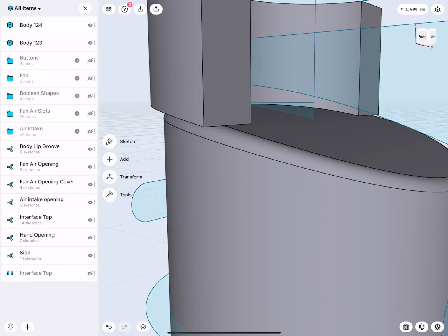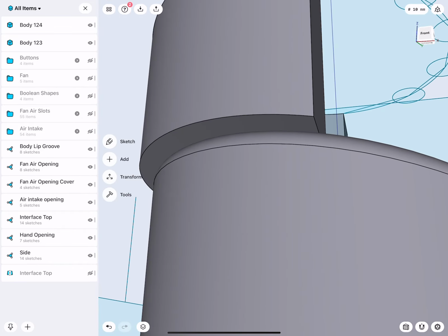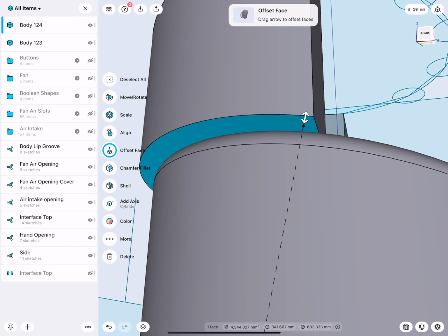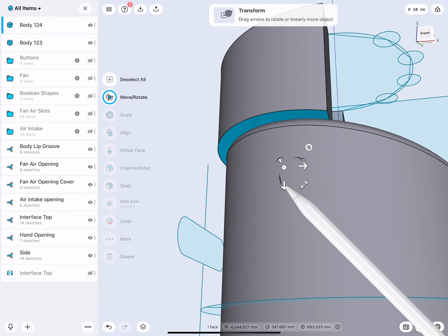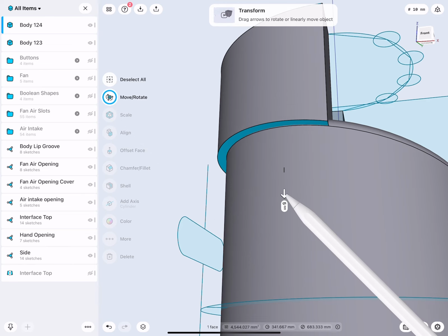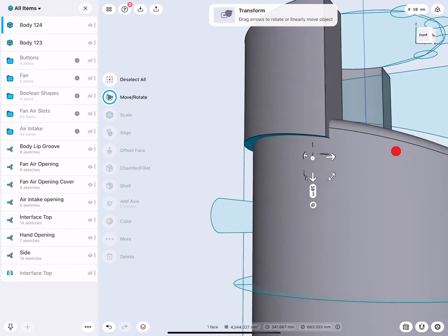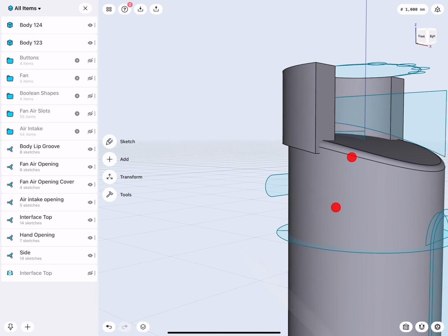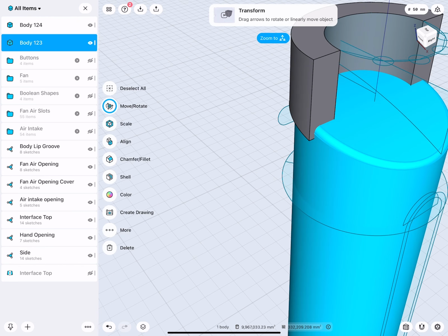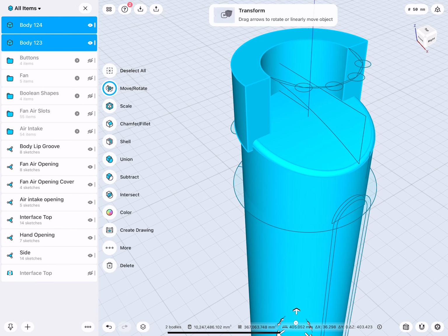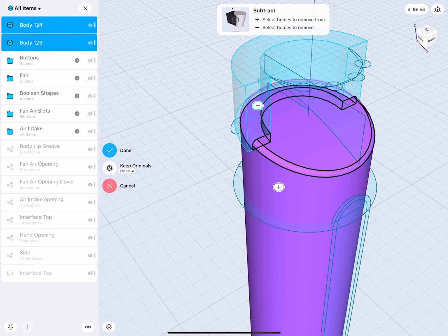While this is now sitting on the face, this has to go a little bit into the face. So similar trick here again. I select this face and I go to move, and this is 5. Let's move this down by 10 millimeters. Very good. Okay. So I will use this shape later to cut, split, remove something from that. So let's do that. I select this, then I select this, and then I say subtract.